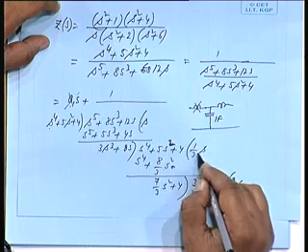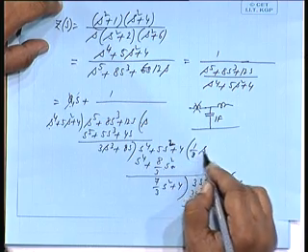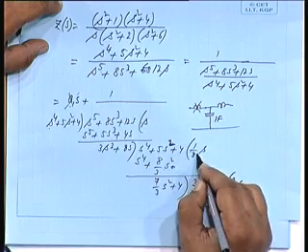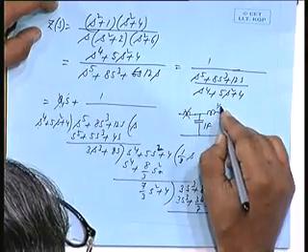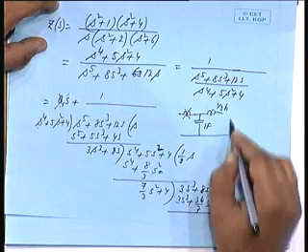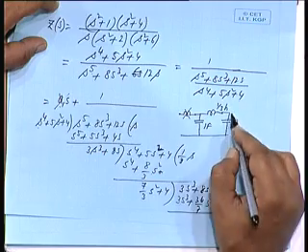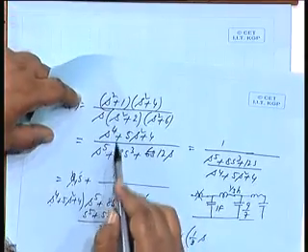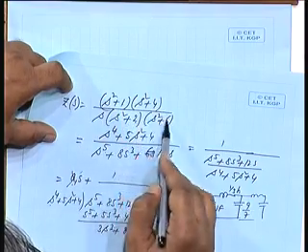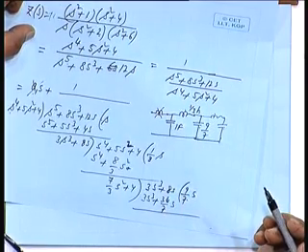Straight away these quotients, the term associated with s, gives you the element values, 1/3 Henry, then 9 by 7 farads and so on. How many elements are there? 1, 2, 3, 4 and a constant 5. So, there will be 1, 2, 3, 4, 5. It will end up like this.